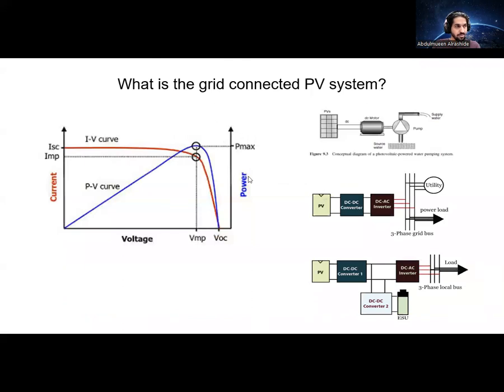First of all, I want to talk about the IV curve, which is the red line in here. Now, the IV curve represents two points. The first point is the open circuit test, which means you apply no load to the PV. You open those two lines and measure the voltage. In this case, it's going to give you the maximum voltage, the VOC, the open circuit voltage.